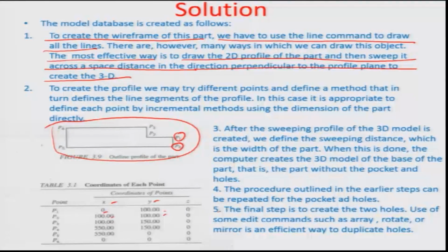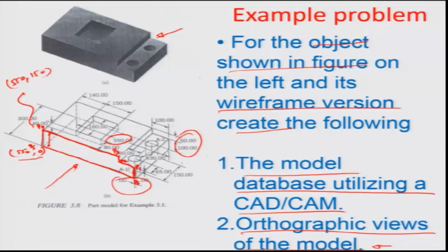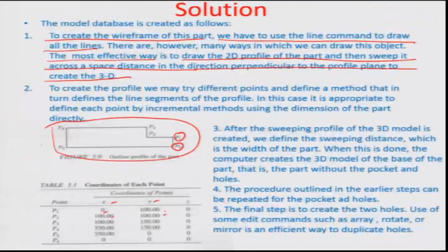You can actually go back to the figure and compute this yourself looking at the different dimensions, and then you basically create steps of z from 0, which is actually this right here, all the way to about 300, which is somewhere towards this corner. So, this is the first step of creating the whole solid block without any of these different cylinders or cuboids extracted or cut out of the particular geometry. So, that is the first step towards creating the wireframe of the solid model.